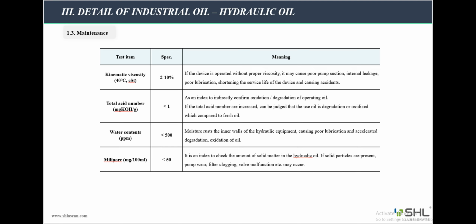The first is viscosity. Oil viscosity is managed around 10% of the change compared to new oil, because if the device is operated without proper viscosity, it may cause poor pump suction, internal leakage, poor lubrication, shortening the service life of the device and causing accidents.